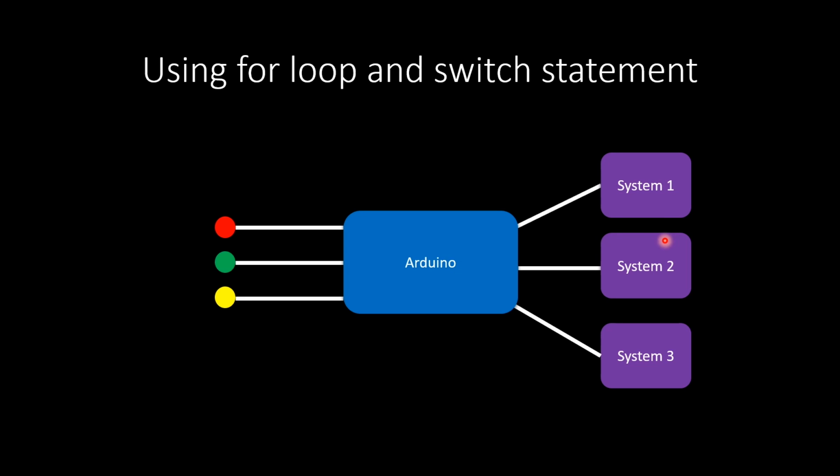So if the reading from any two potentiometers is above 500, only then the LEDs will glow, right? I'll keep changing the values of these potentiometers, and Arduino has to analyze the values it is obtaining from the peripherals, like these three potentiometers, and turn the LEDs on or off.